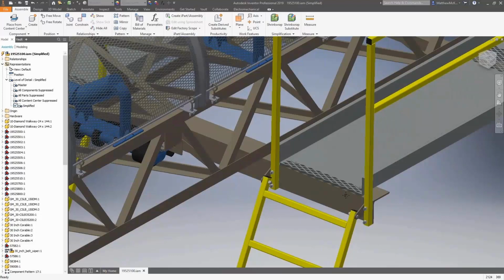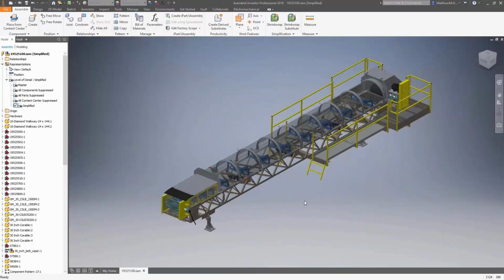But you'll notice there's a couple of different modeling techniques that can flow on to have an impact in your design. Pause for a moment and think, well, what happens if we hadn't used that? How would we have displayed it? Potentially, we would have had to display it as a note on a drawing, or use a visual representation or a visual cue here. Or in some instances, like I've said before, people will model in the full detail like they do with threads and so forth, but that can add a significant requirement to the capacity of your system to be able to handle, and that could quite easily turn what is a relatively easy assembly to work with inside of Inventor into a very difficult one.